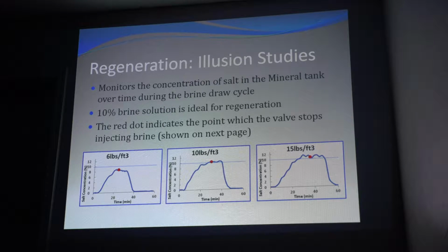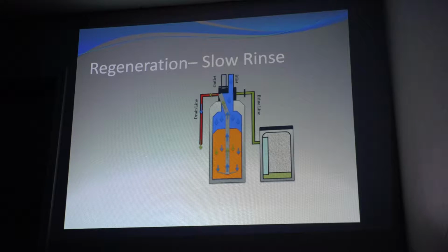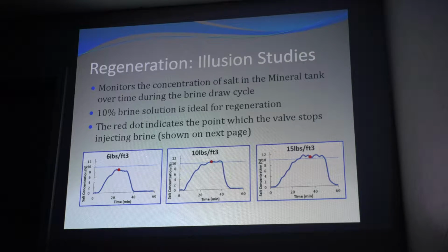I was going to ask you, I've got a huge water softener. Is that the same curve that I've got for my huge softener as it is for my home softener? Absolutely. The timing is the same whether you've got a very large water softener or a small water softener. The reason being is we size the injector and the drain line flow control accordingly.